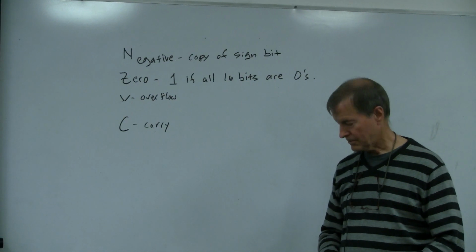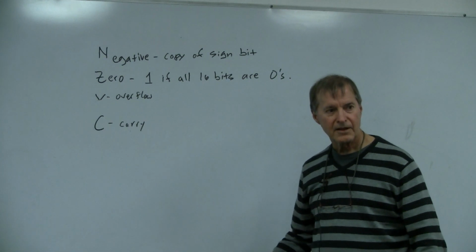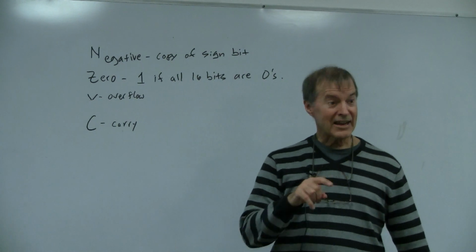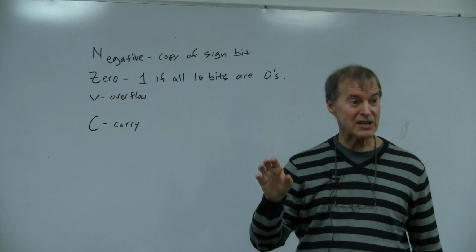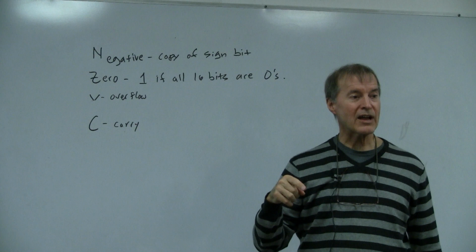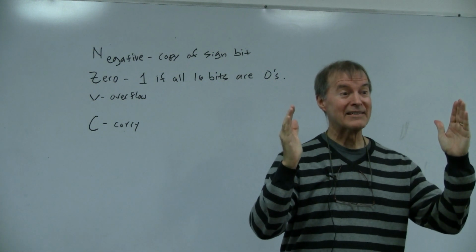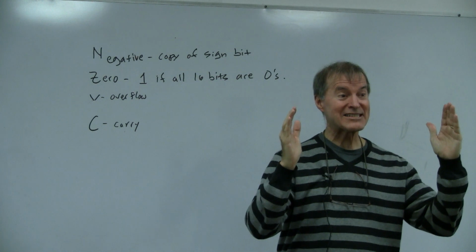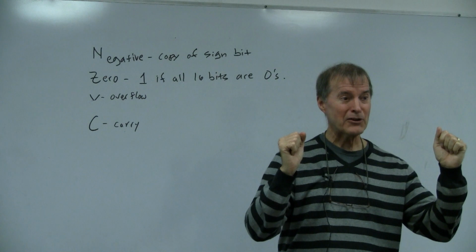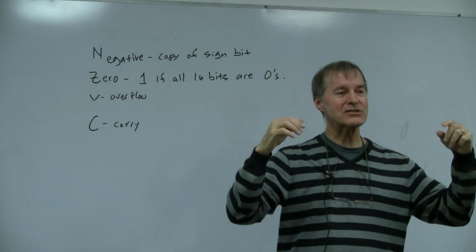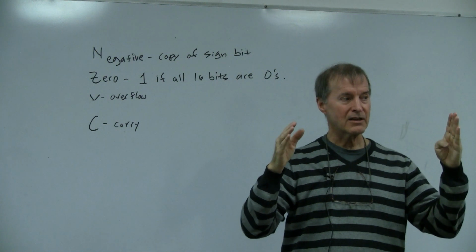Isn't the result 8 bits? Yes, the result is 8 bits. A bus is 8 bits, B bus is 8 bits, and result is 8 bits. But as far as the user at level ISA 3 is concerned, how big is the accumulator? It's 16 bits. Are you with me? And when we did those calculations of how to calculate Z, what did we look at?